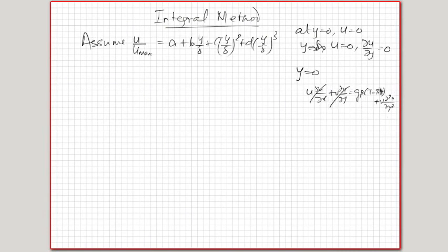So then this becomes this. So I can write g beta into T wall minus T infinity, because at y is equal to 0, T is T wall, plus mu del squared u by del y square is equal to 0. Okay, so this is the condition that you will get in addition.